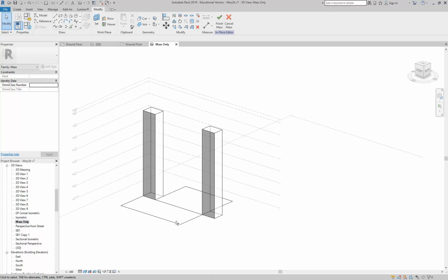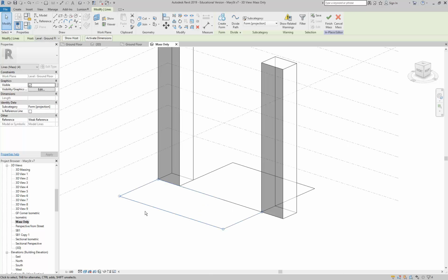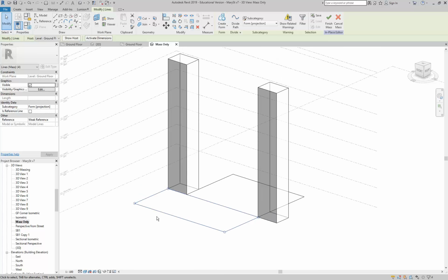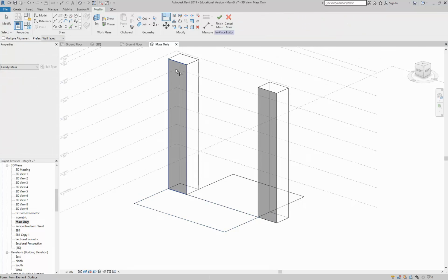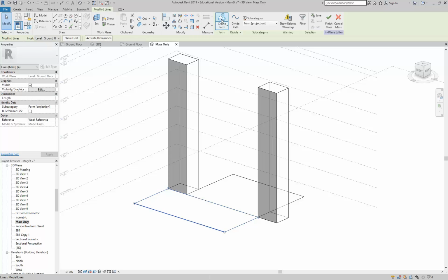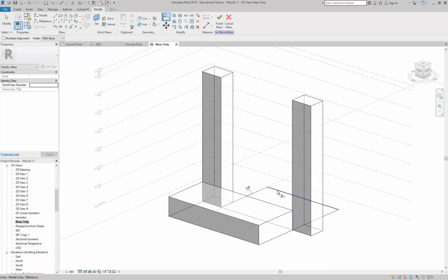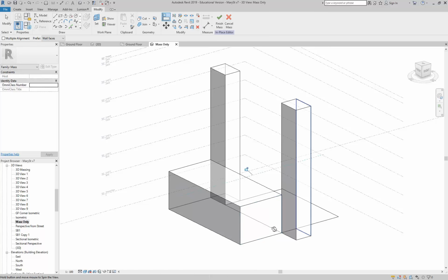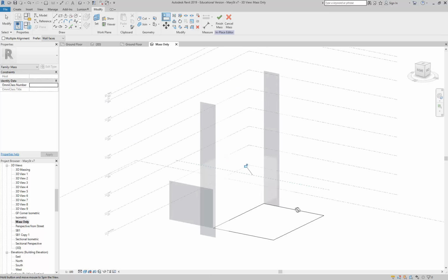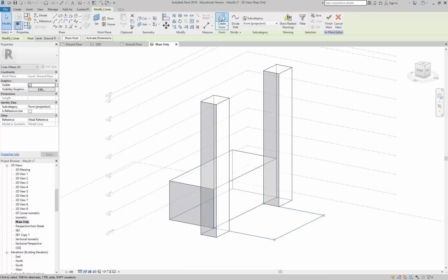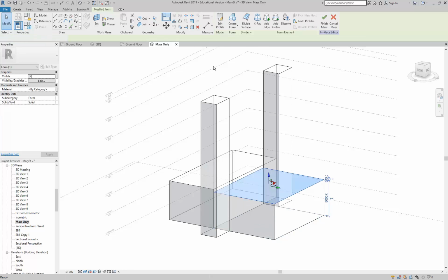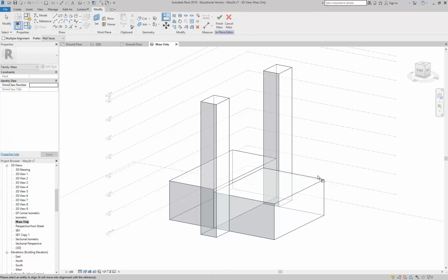So I've got these basic massing shapes, and then the foyer might only be, let's say, not a mezzanine, but open to the level above, so again, create form, and then align it to level 1, level 2. And then let's say this back part is only 1 story. So again, create form, and then align to level 1.